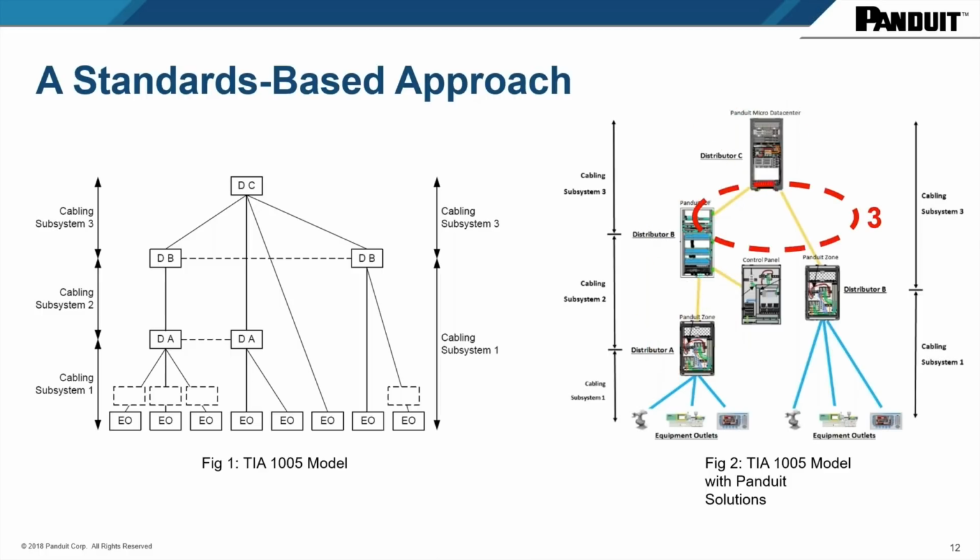Connectivity between these points also is something to worry about. So generally in a star topology, communicating from a control room to a distribution frame outside the factory systems, the distance between that micro data center and a distribution point on the floor can be a long distance. Generally, cabling between those two devices is fiber.